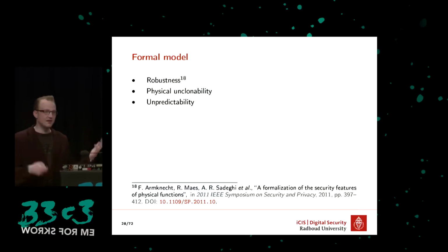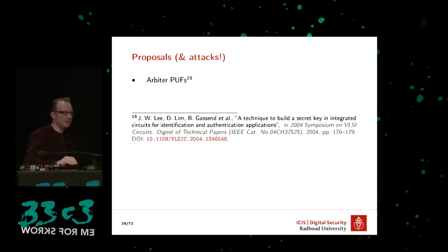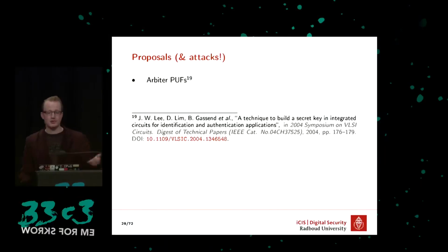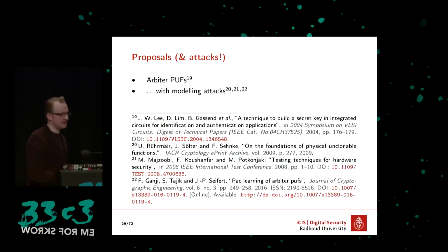And since then, since 2001, there have been a lot of proposals and attacks on PUFs. So first, there are the arbiter PUFs, which are all delay-based. So the general idea here is that if you run a signal through a chip, it's delayed by a certain amount. But the amount is unique per chip. But it turns out that you can pretty easily model this.